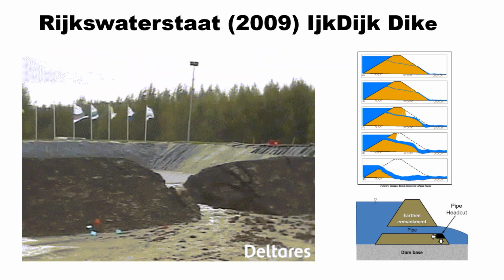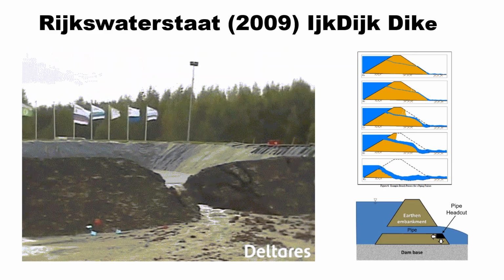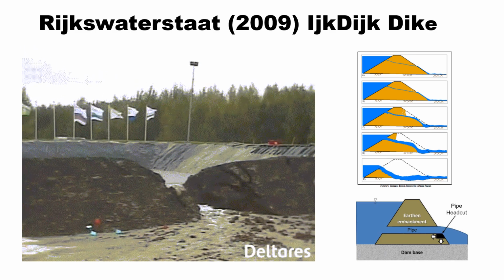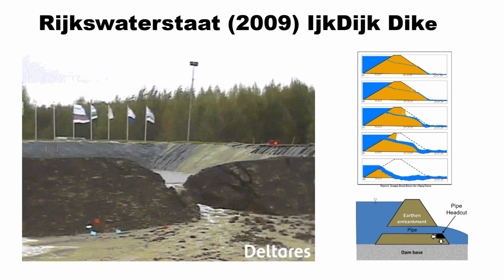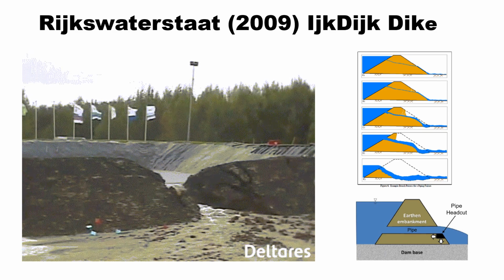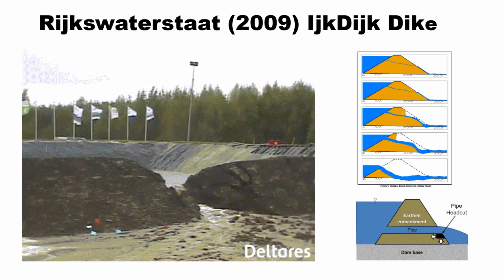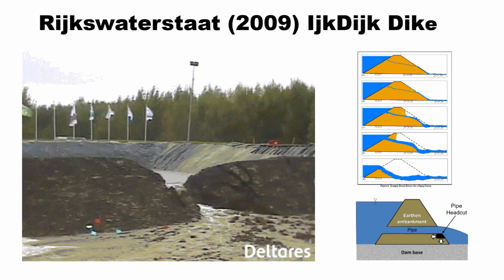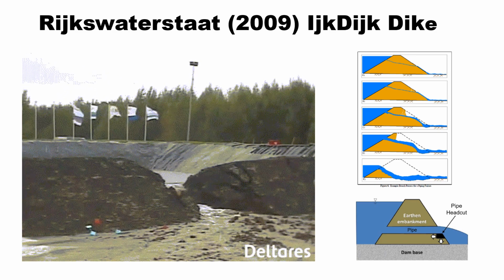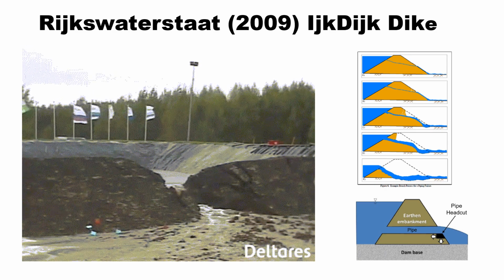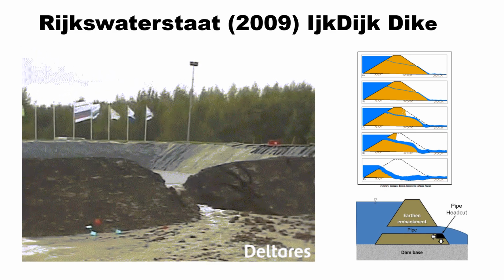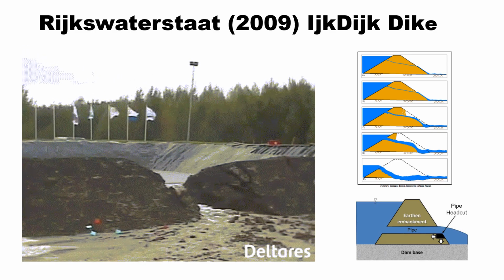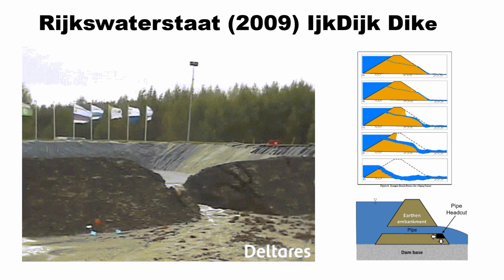Here is a better look at the extents of the large-scale test. At this point, the crest is lowered with the embankment collapse into the developing pipe. The freeboard is then exceeded on the deformed crest overlying the pipe, and overtopping ensues. Here, a couple of head cuts are observable as overtopping erosion continues. Multiple head cuts appear to have now merged into one larger head cut. And here's the final breach width at the end of the video.